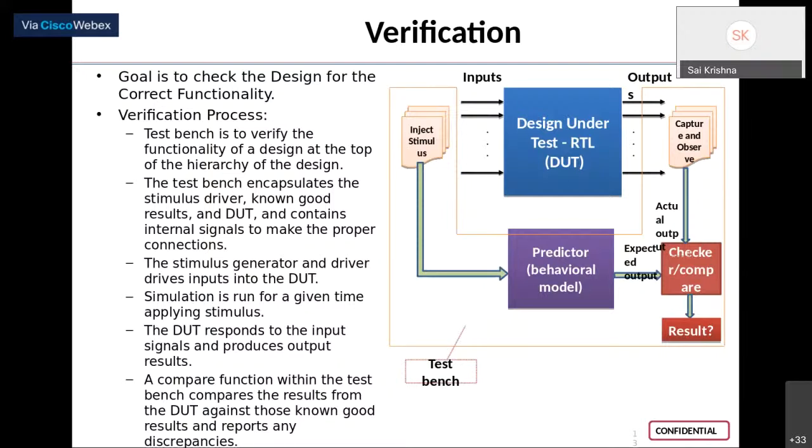Okay, so here your DUT, which is your RTL program containing the logic, and your test bench, which contains your inputs, both of them are connected using a process called instantiation. That means you call your RTL code or your RTL main module into the test bench, that is called instantiation, and force all your stimulus, your inputs, onto it, and see what the output is. Next.